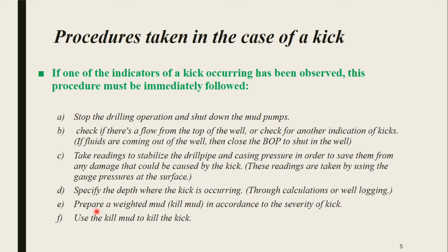And then prepare a weighted mud, also called kill mud, in accordance to the severity of the kick. For example, if the kick is very severe, then you have to prepare a mud whose weight is very high so that it can be able to kill this kick. And then finally, use this kill mud or weighted mud to kill the kick.